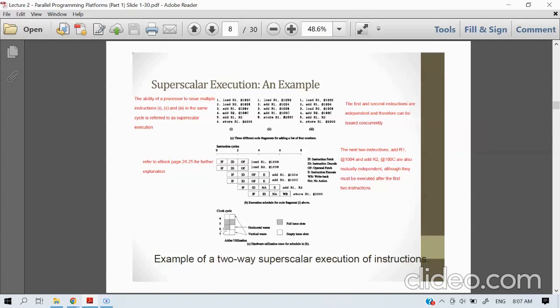So that's why for time slot 6 only one issue slot is being used, and the other one is not being used. How about time number 7? It is WB, which is write back, so there is no operation being executed. The issue is there is an empty slot, so actually it's a waste here, right?